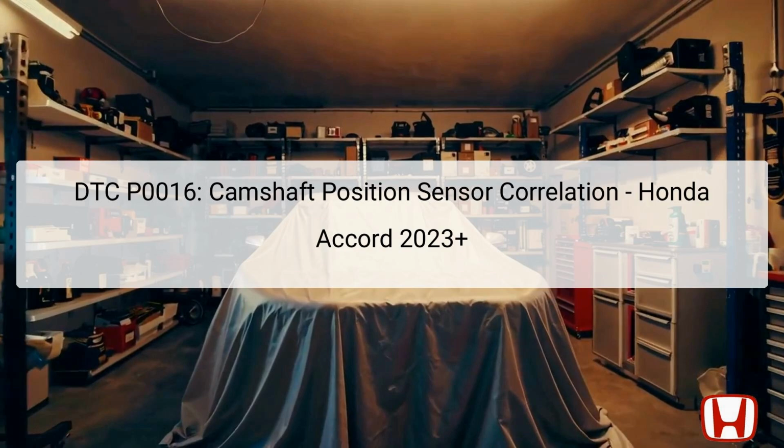or increased emissions. The Powertrain Control Module, PCM, will store this DTC when it detects that the phase of the intake camshaft is outside the specified range compared to a standard phase value. It's crucial to address this error promptly to maintain engine efficiency and vehicle safety.